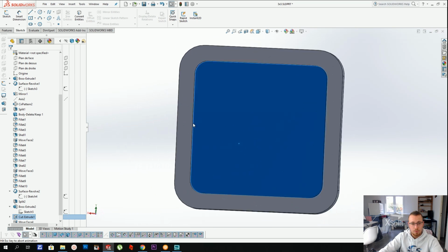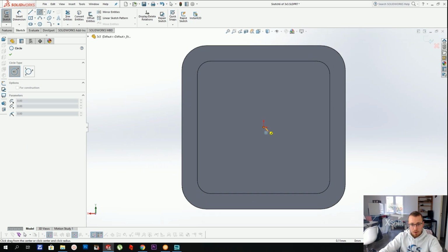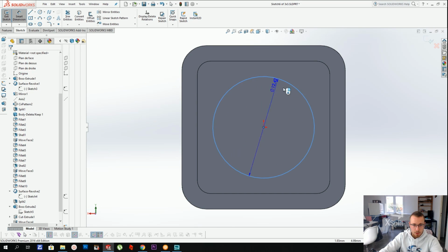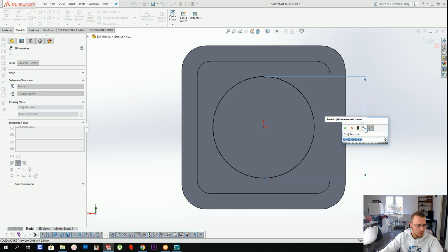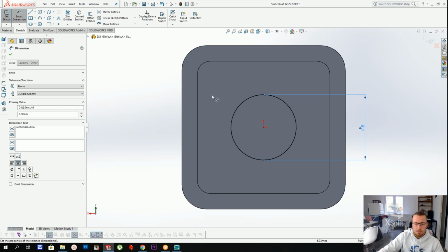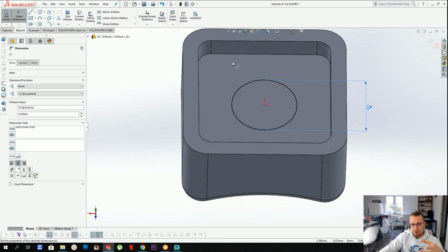Now you need to drill a hole for the screw. Now if you do M2 screws, you need to have a diameter for the head of about 5 millimeters. Here I'm going to use M3, so I'm going to use 7 to 8 millimeters. It doesn't really matter, you're not really centering yourself around the head of the screw. You can have a little bit of leeway because the puzzle is actually going to center itself around its geometry, so it's going to be fine.